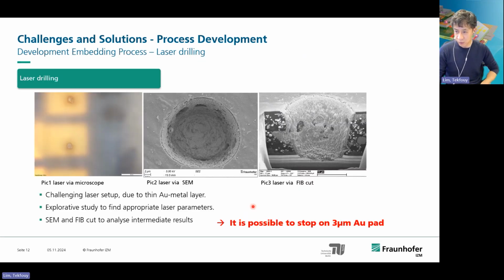And on the laser drilling, you can see that we go here, and then the IC pads are here. Then we see that we don't destroy the pads, and we have the connections here. And here are the cross sections after the laser drilling, and you can see that here we can drill until the gold pad without damaging the 3-5 material below.